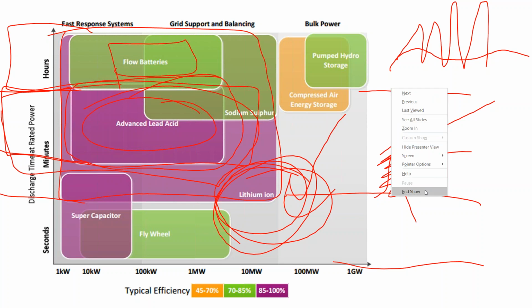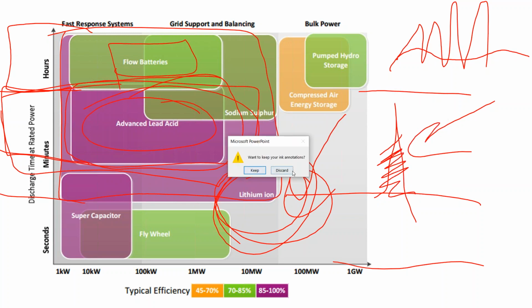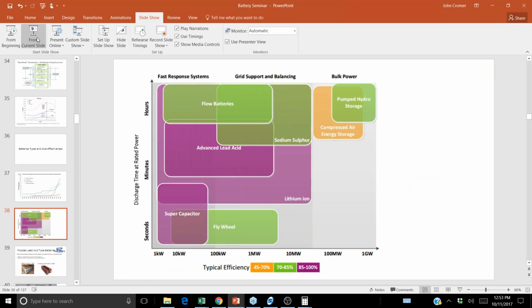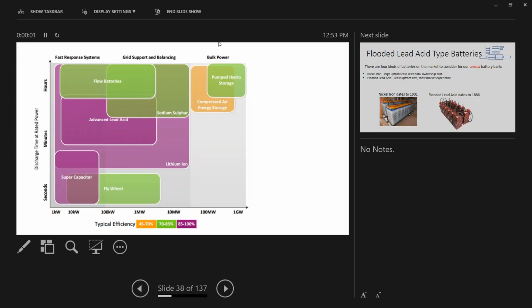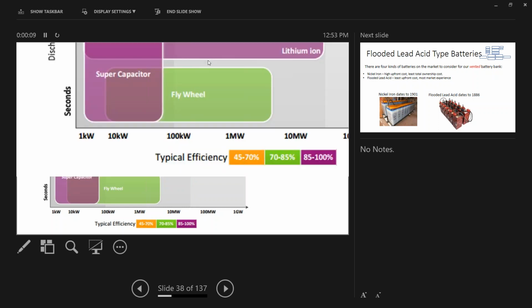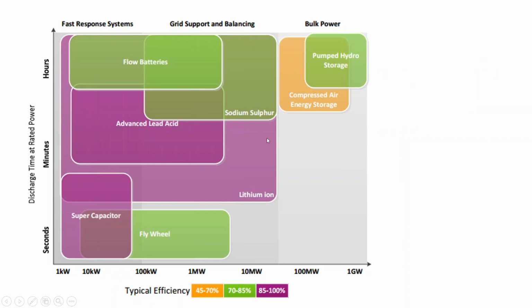And so on our off-grid home, we're using lead acid. What that means is we have to be very cognizant of, hey, if we're buying a refrigerator, can we get a variable speed frequency drive in that refrigerator, rather than it having a duty cycle where it clicks on and clicks off and clicks on and clicks off? We might have it so that the duty cycle runs continuously throughout the day, and that would be less stressful on our lead acid battery bank.